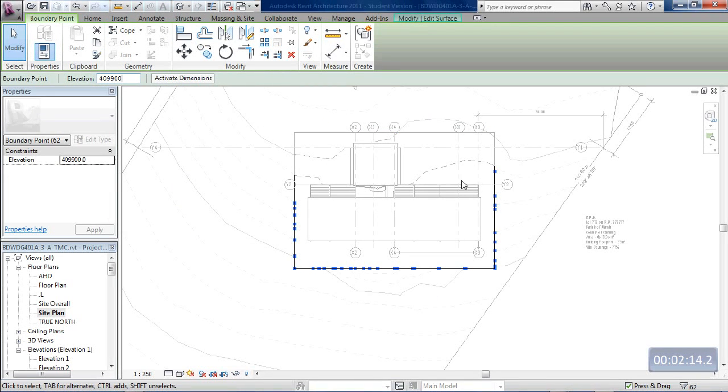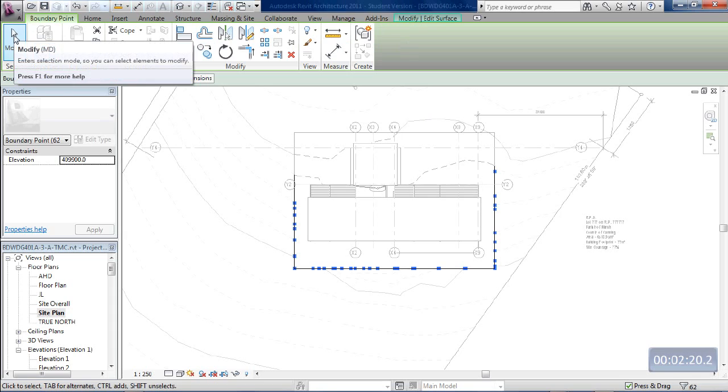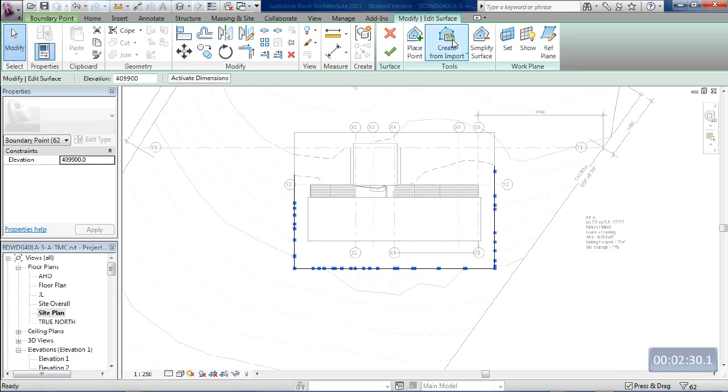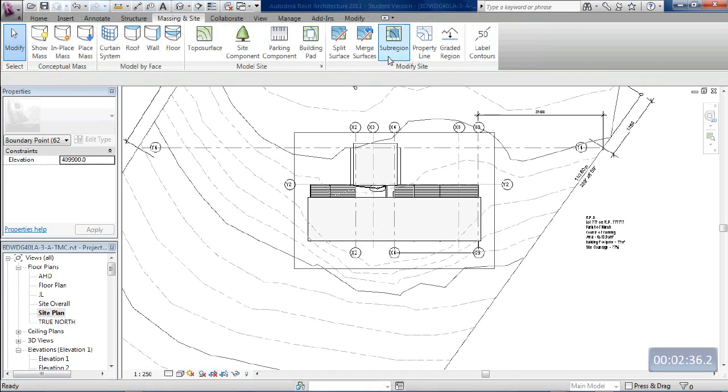I can't see the tick menu up through here, and that's just because every so often when you do go to something like select modify, it navigates you away from the menu you were on. But the menu you were on will always be highlighted in green. So always look for that green menu, click up there, and now I can see what I expected to see before, which was this tick. So click off the tick, and we've finished that command.